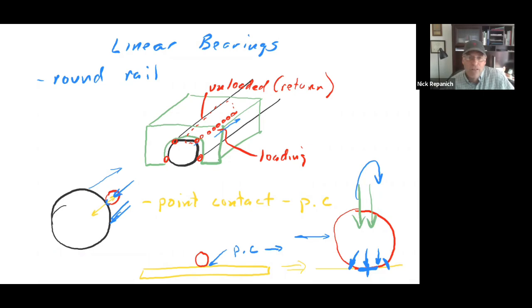but this is such the basis for everything that you deal with when you start here up to designing a mechanism. When you preload this bearing, you look for something that doesn't slide, that rolls most of the time. So far we have point contact to point contact. We've had point contact to flat. Neither of those are we going to use very often.